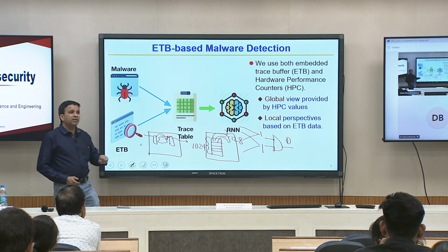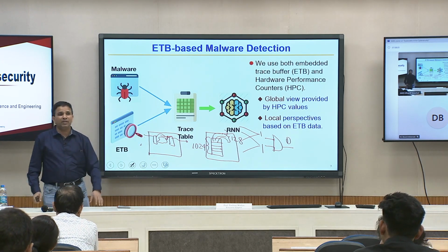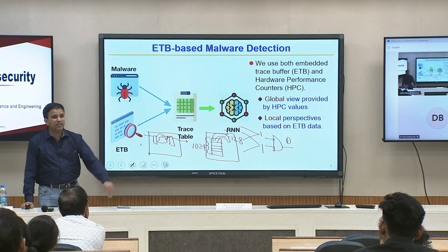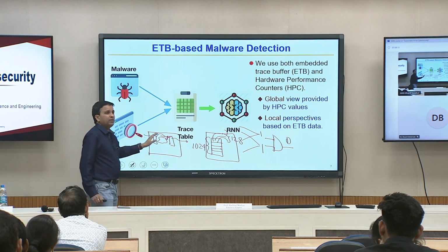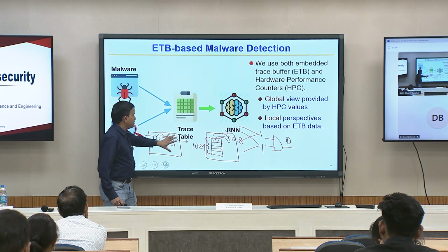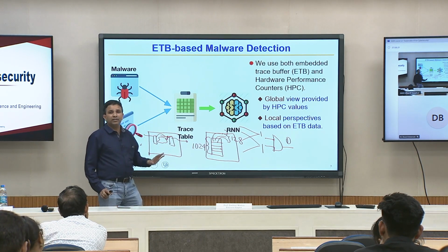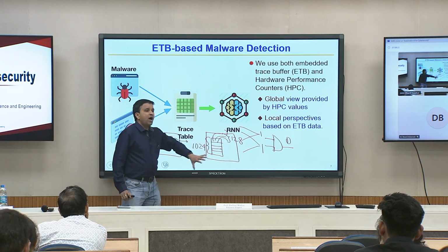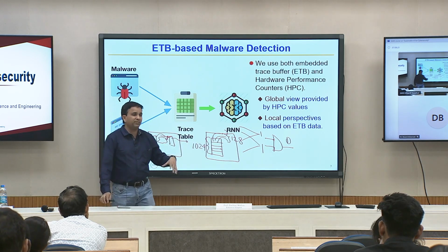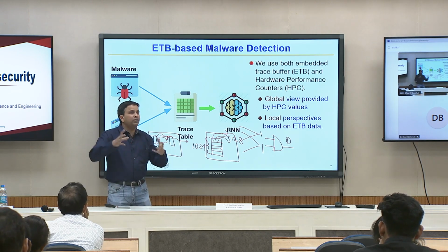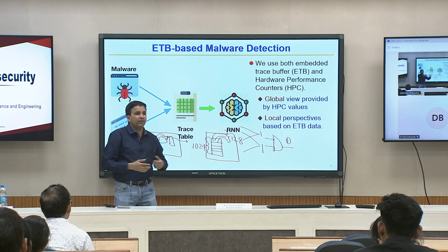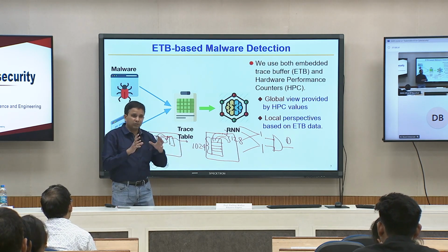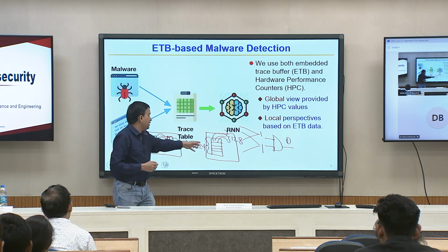How do they take advantage of the scan chain? Can anybody tell me? We talked about it on the day of assertion based validation. In scan mode, the time when this is used and the time when the trace buffer is used are totally different. This is typically used after it is manufactured. Let us say the chip is manufactured, you built a robot, and that robot is used in an Amazon facility to carry stuff to the truck or wherever, and something went wrong. People would stop that robot, download this data and test.